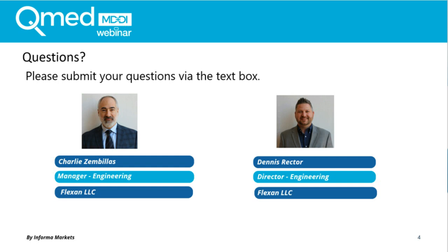And the issue is that when you open up the package in another facility, even if it's a clean room environment, there still is some level of fiber and particulate. So right before the coating application, you clean it with alcohol, let it air dry enough for your coating, and that should solve your problem. All right, thank you, Dennis.